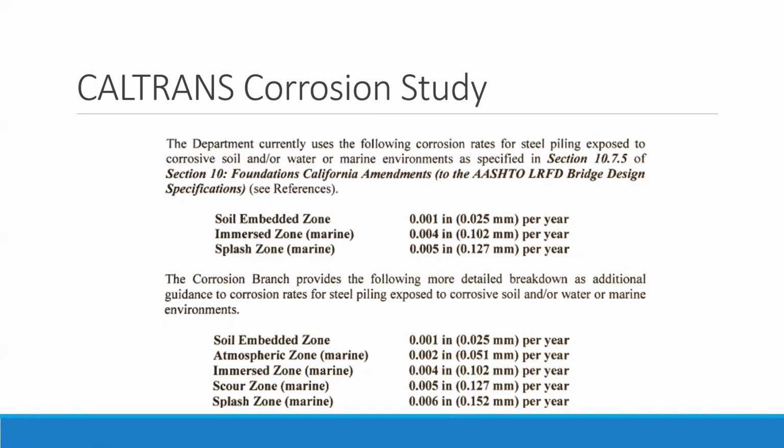And the department cited that sacrificial metal be incorporated into the design of the pipe wall thickness to compensate for the loss of metal that occurs due to corrosion. So this extra metal thickness should be added to all surfaces of the pipe that interact with soil and water. At InfraSteel, our design engineers used this type of data in order to determine the necessary wall thickness and sacrificial steel needed to achieve the desired design life.